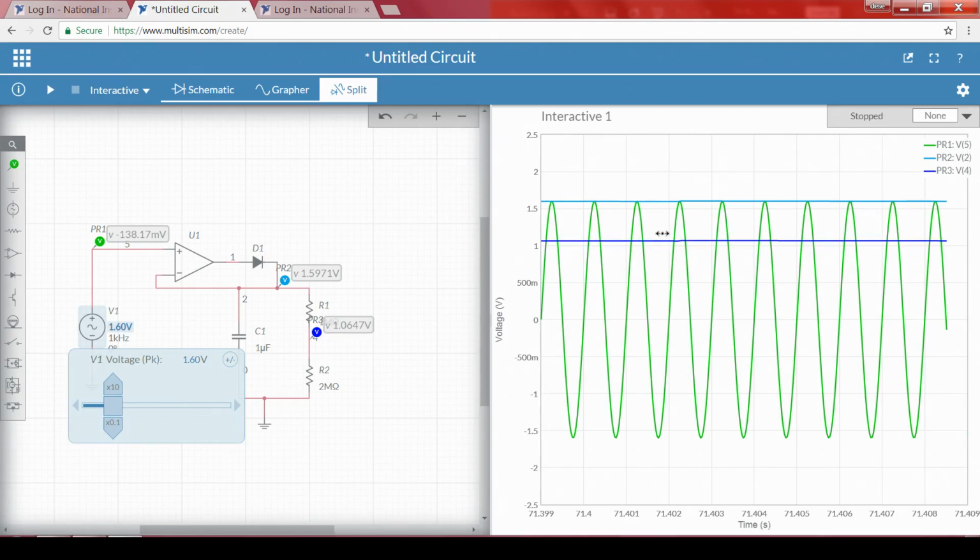A simple comparator is enough. We do not have to go with any Schmitt triggers or anything. The reason is, we are not setting two thresholds here, we are using only a single threshold. If the input value is greater than this particular value, only that signal has to be passed, detected, and counted. Depending upon how many such pulses we are getting, if you use a counter there, then we can automatically see the number of pulses we are getting per second or per minute. Now, in order to do that, we will implement the other part of our circuit.